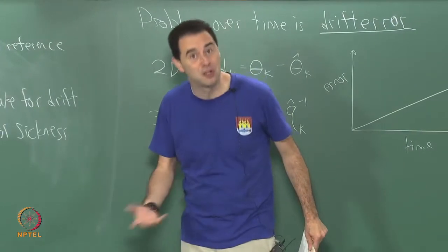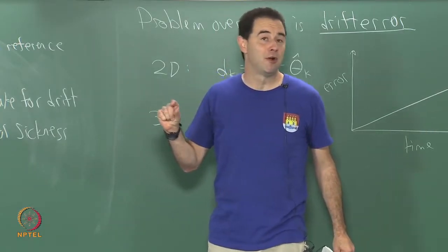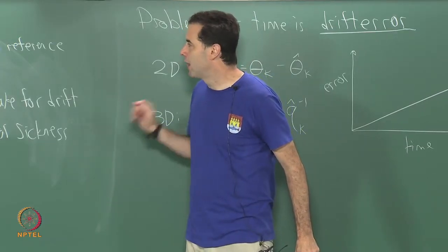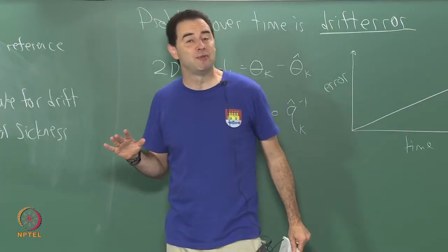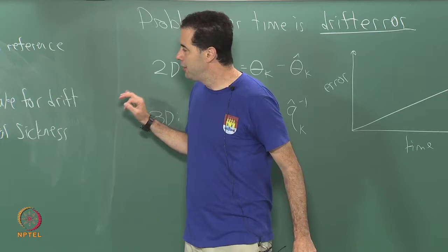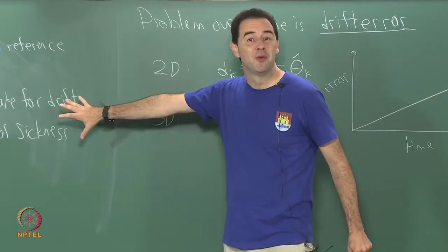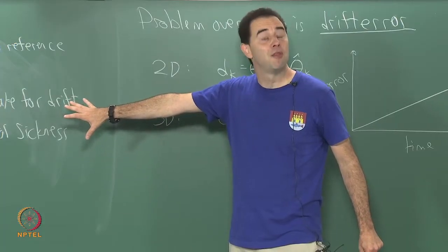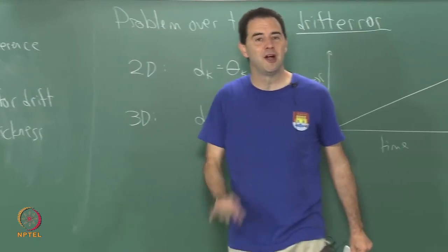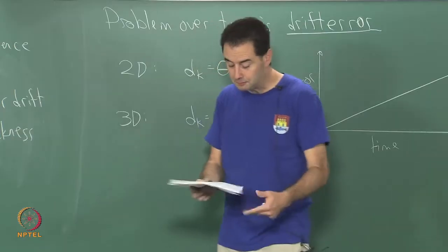It turns out we're very fortunate in today's world of MEMS-based gyroscopes that appear on our top-of-the-line smartphones these days, that the gyro quality, especially if the gyroscope has been very well calibrated, especially for temperature dependence and other factors, then the growth rate ends up being slow enough so that it is possible to compensate for this without, as far as we can tell, without perceptual side effects causing simulator sickness. So we're very lucky to be in this kind of regime today where we can in fact accomplish this.